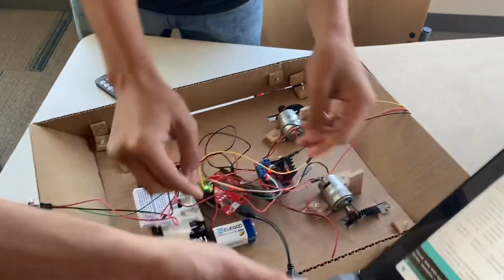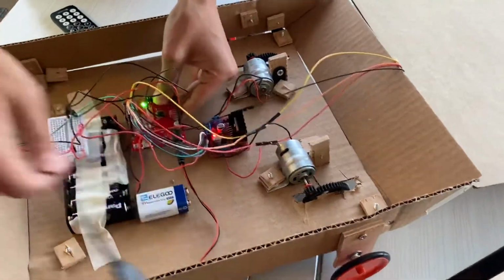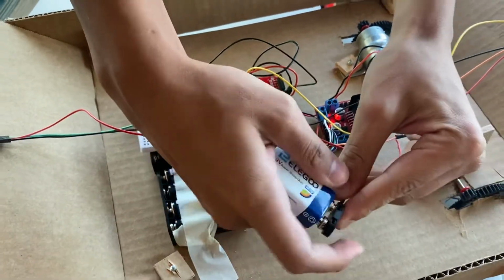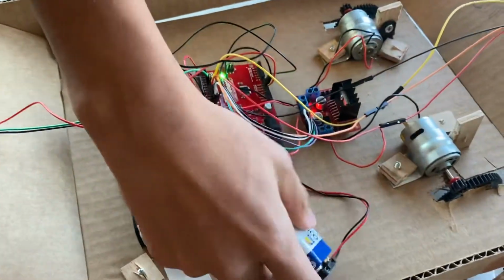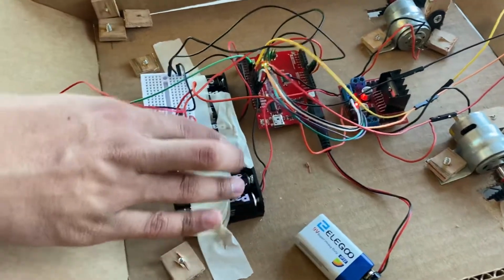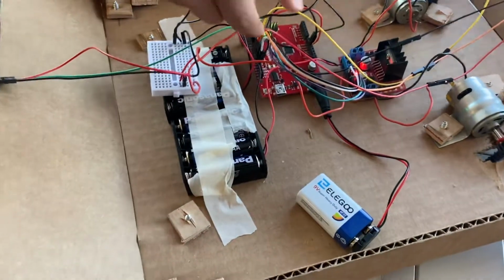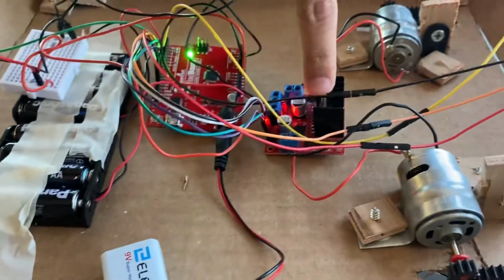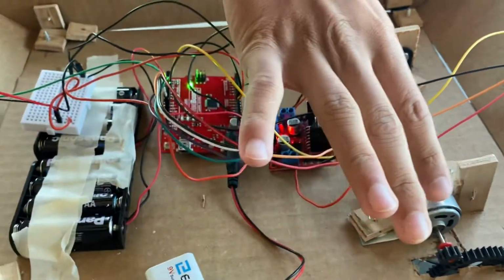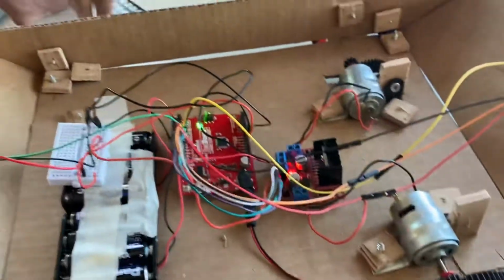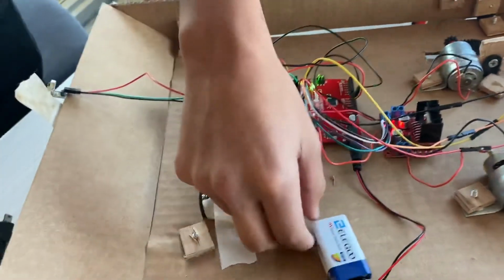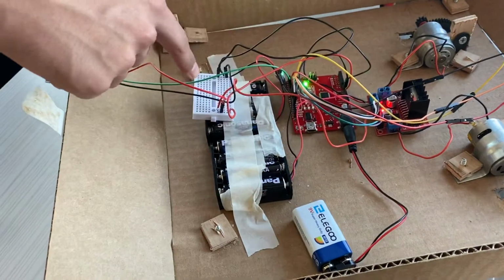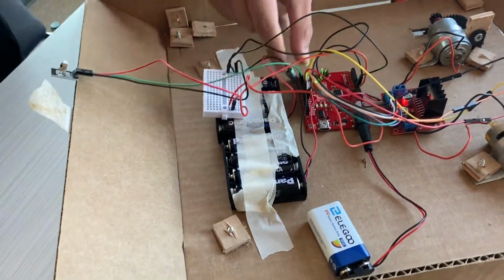Okay, you could disconnect that now. So we have our Arduino board, which is connected to this 9 volt to power it. And then the motors are powered by this pack of batteries over here. So from our Arduino, we have 4 wires connecting to this motor board, which both connect to both of our motors so that they're independently turning. We have the wires linked to the breadboard so it can connect to the Arduino and simplify the circuits.